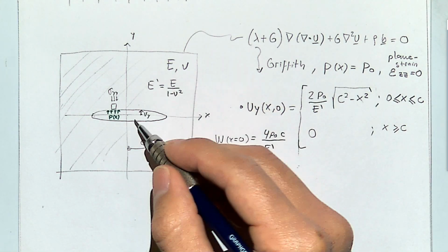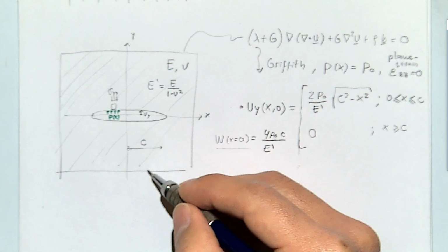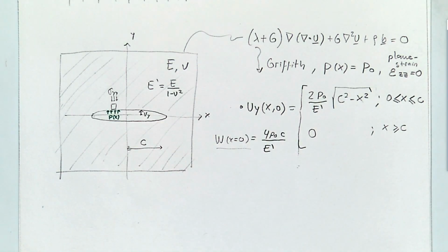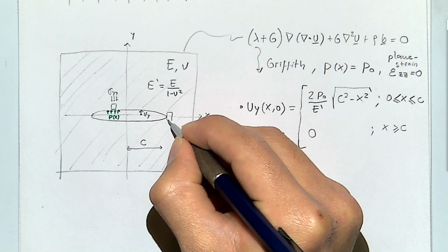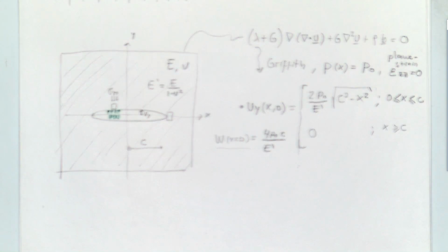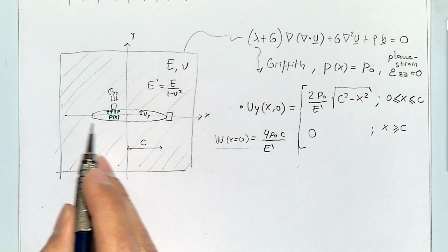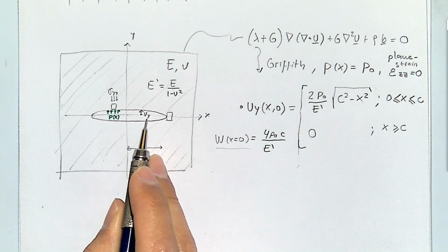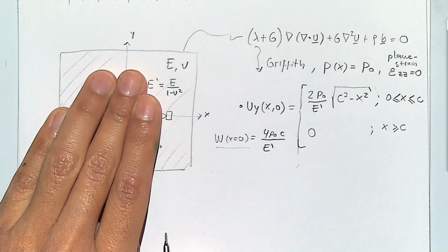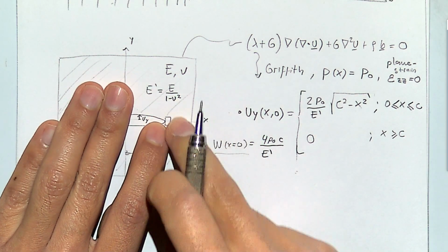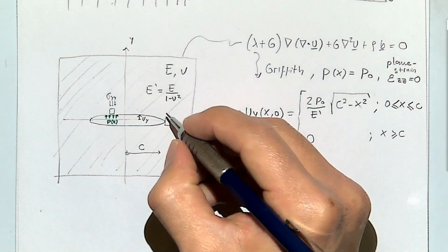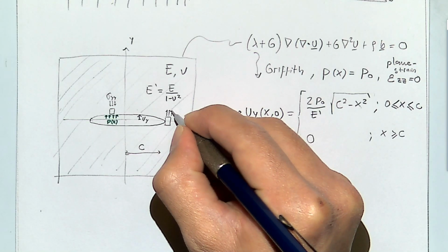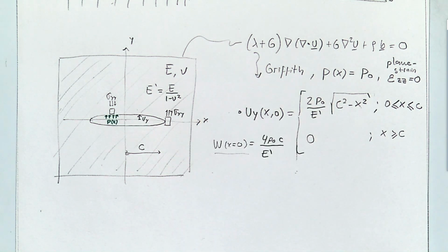On the wall of the fracture, we have compression because the pressure is pressing against the fracture. But at the tip of the fracture, we're going to have tension in order to equilibrate all this pressure. So all of this pressure is pressing up. There is something that has to pull down the solid so it doesn't split in two. So here, we're going to have a tension.